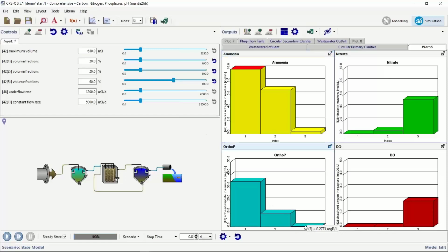So let's see if we can get this down even lower. Let's give it a little bit more of an anoxic zone to get more release before the uptake. So that means I've got to shave another 10% off that. And let's see how that goes. So are we still okay? 0.5, almost 0.6. Okay, well, we're still under 1. This is now dropping again. So that's gotten us below 0.2.